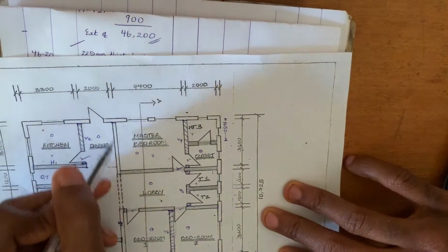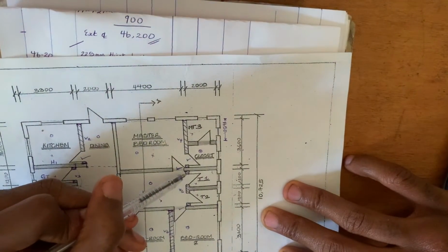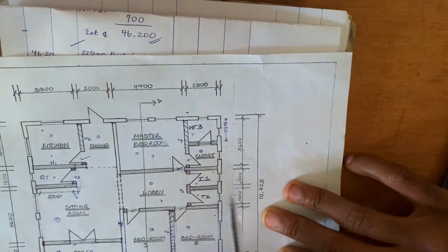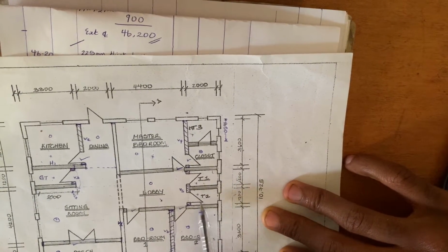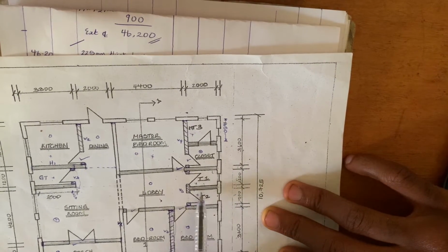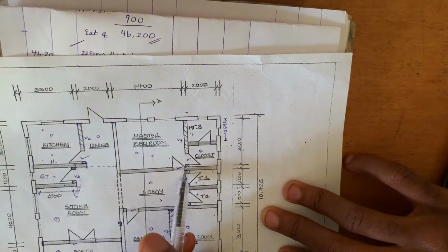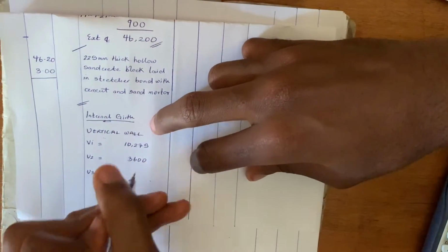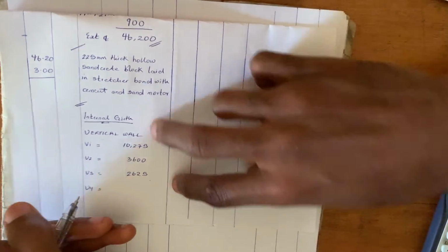Then we go towards V3. Now I have done for this entire block here. So next we'll take this block here. Now this block is the summation of the end-to-end dimension for toilet 1, the end-to-end dimension for toilet 2, and this block thickness here. So we're going to be summing 1,200, 1,200, 225, and 1,200 to give us the entire length of this block here. So we get 2,625. So we go to V4.